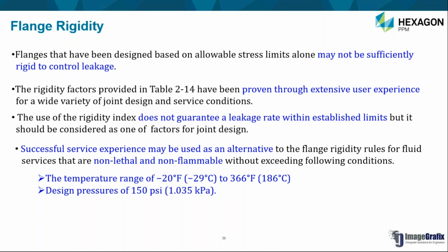Okay. Another point over here, there is one alternative, or an exception given, where it is allowed to waive off the requirements of the flange rigidity. So if we have any past experience of flanges which are still in service, and those were designed without rigidity index, and they are serving for a longer period of time, so we can have that advantage provided none of the following conditions are violated. So what are those conditions?